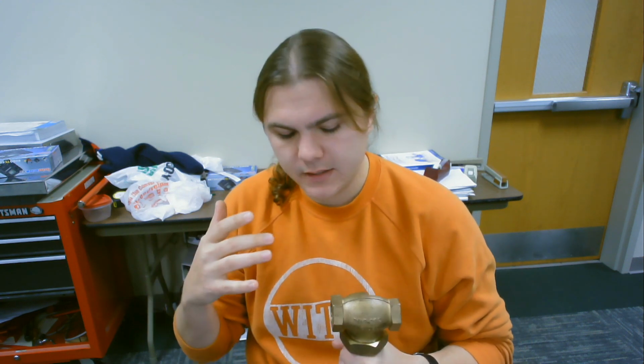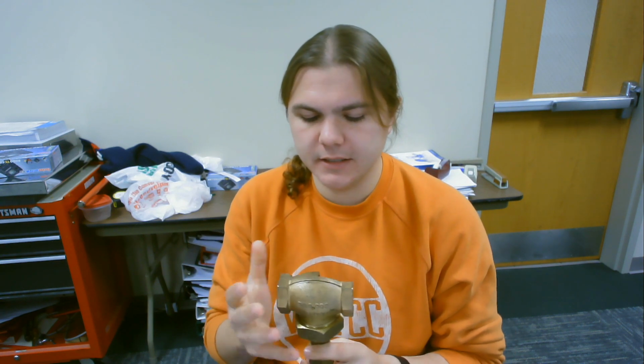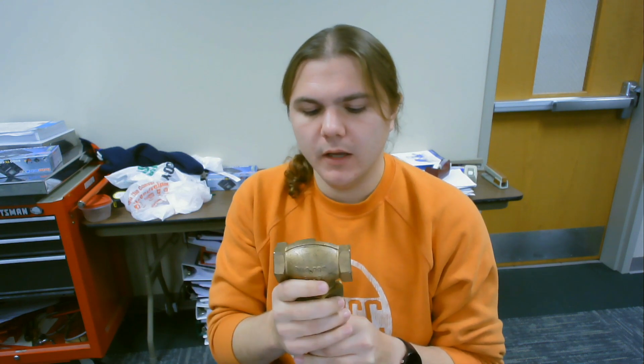So there are going to be some parts and assemblies out there that no matter what view you use, be it the front, right, top, back, bottom, whatever, you're not going to be able to dimension to certain features inside of it, internal features. And when you come across those situations, which some of you already have, you're going to need to use a section view.